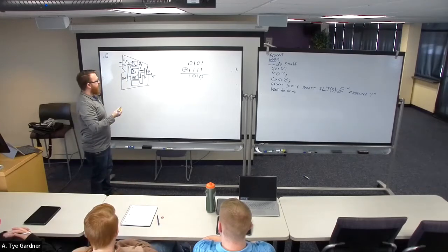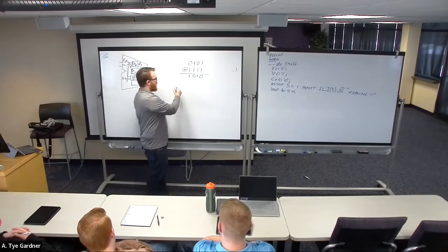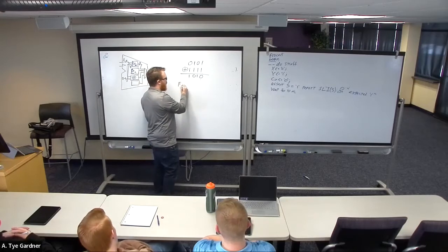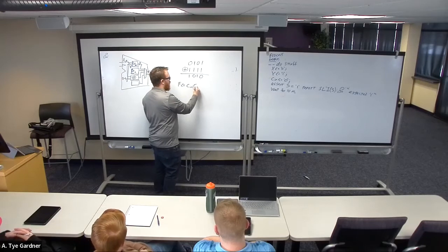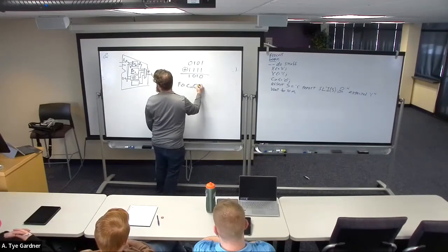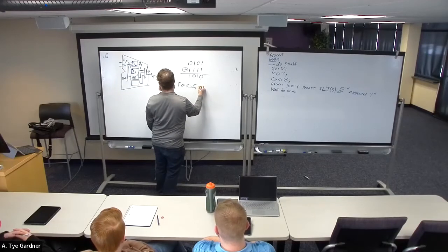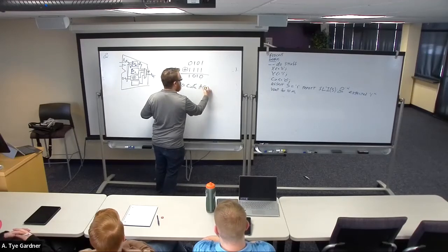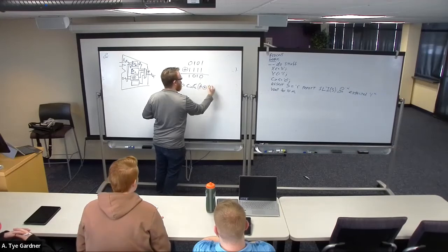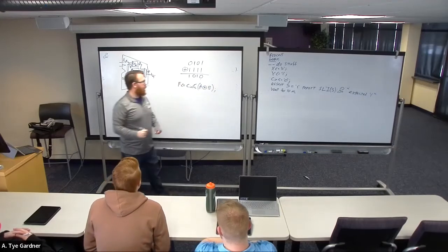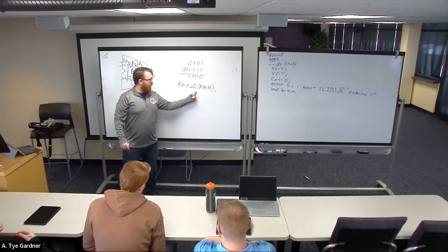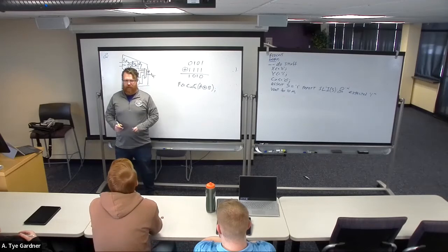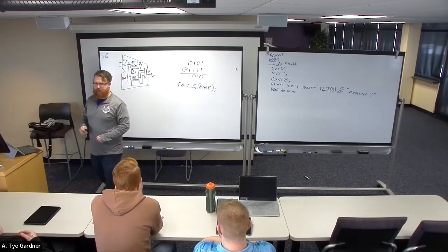And so what we're going to say is if the output of this XOR is F, it's going to look something like CN ampersand A XOR B. Now it's 9 bits, right? Because I have an 8-bit result concatenated with a 1-bit. That's what we're going to do.